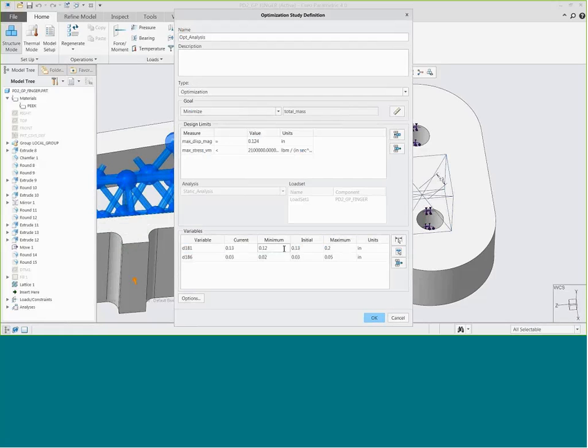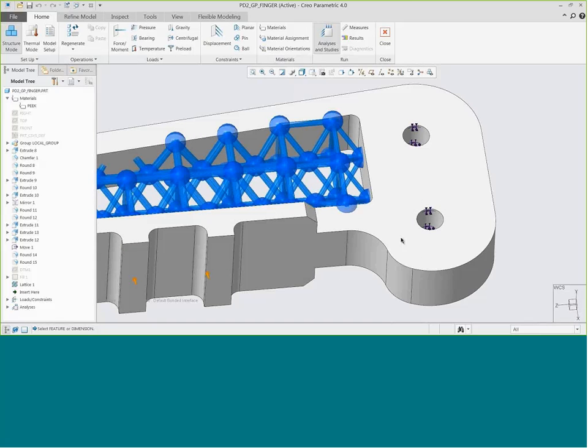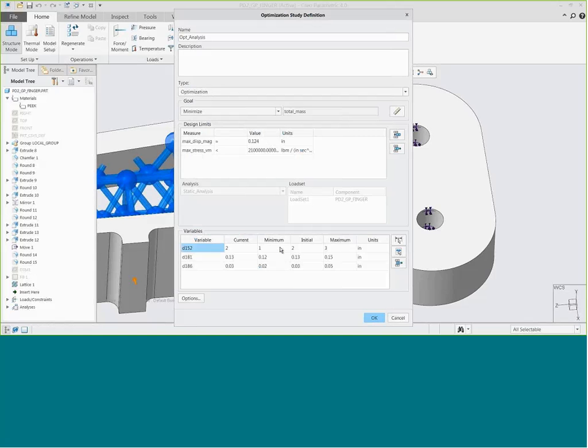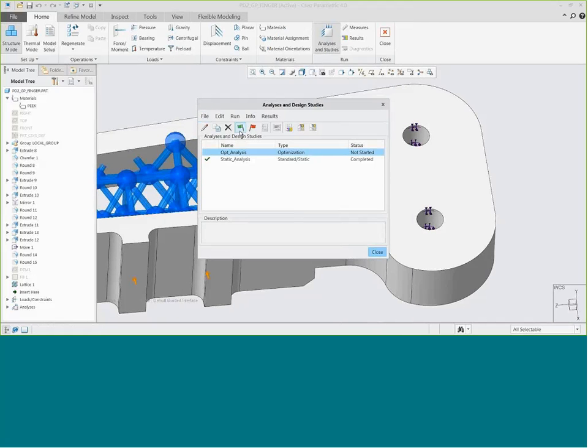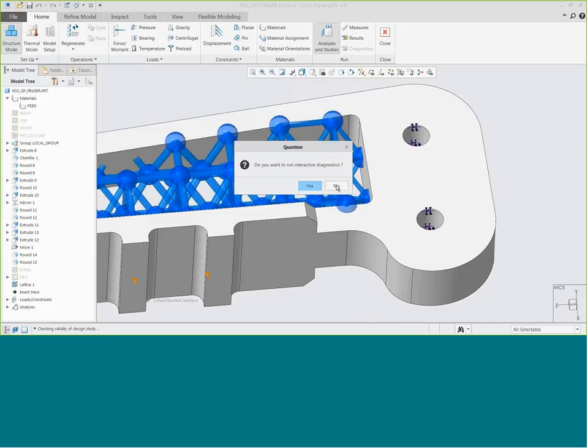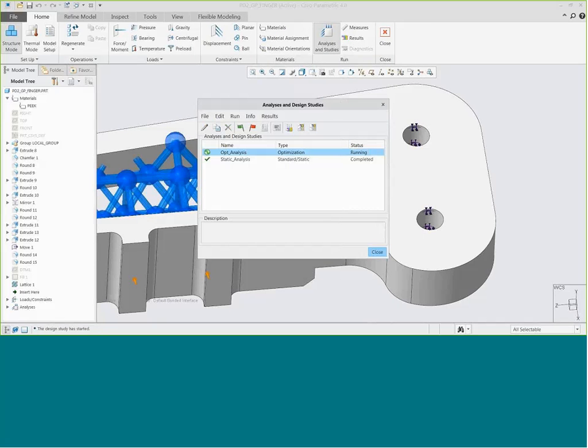And the diameter of the ball in the middle, 0.012 to 0.015. Its initial value is 0.13, so we're changing that by, again, roughly 15% there. And let's change the point at which we vary the mesh from being this heavyweight mesh down to the lightweight mesh on the other side of that dividing plane there. And then having got those variables in there and the parameters that we want to optimize with respect to, let's go and start the design optimization.